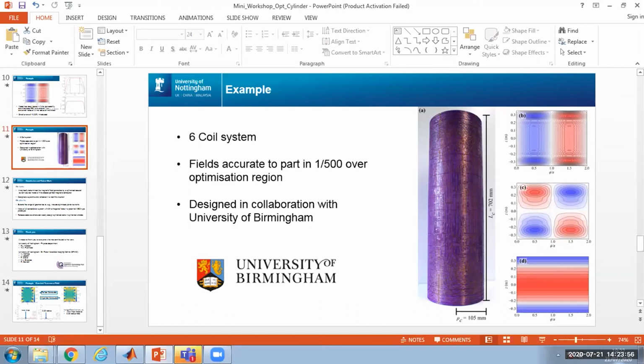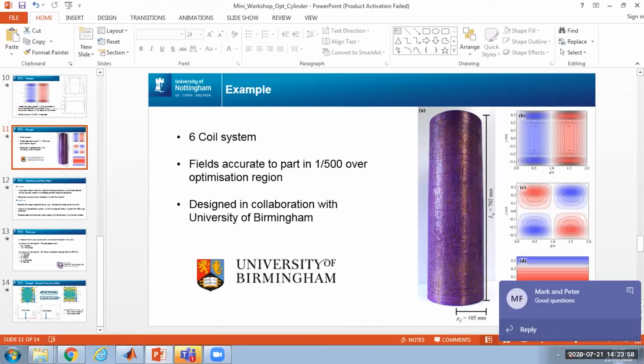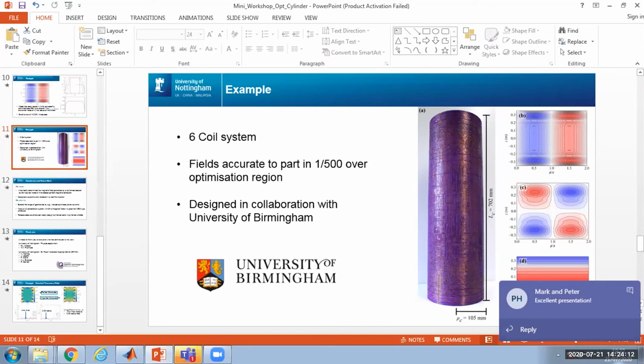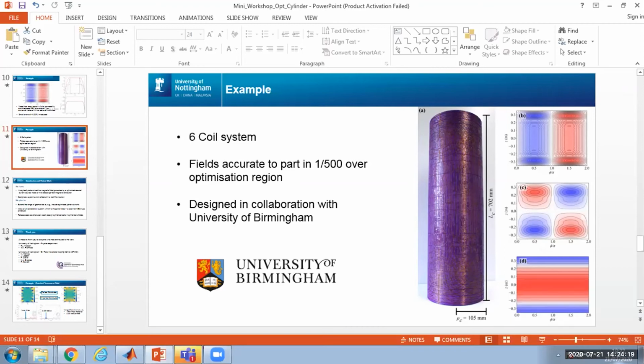They can make them as long as you want, but they are limited to, I think, maybe 60 or 70 centimeters. But that's just Trackwise. I think other companies can make larger PCBs, but I'm not 100% sure. So if anyone knows anything more, please feel free to interject.